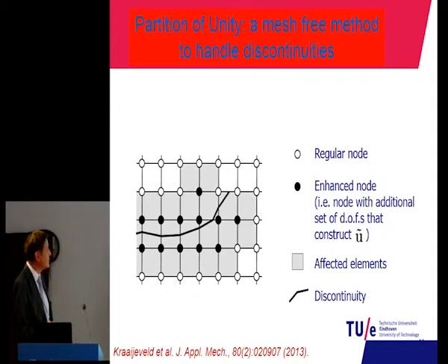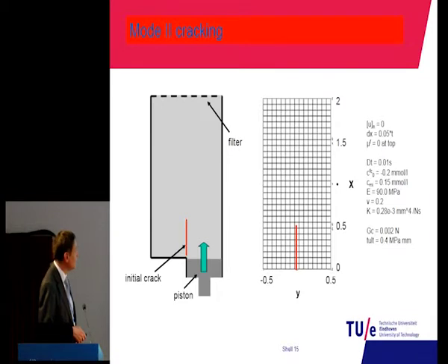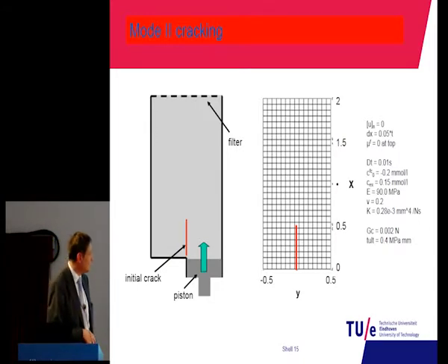And we assemble our system this way so that we can actually eliminate the fluxes element by element and be left in the whole system of equations only with displacements and those three Lagrange multipliers that we use to get these fluxes strictly mass conserving. It is lambda f, lambda plus, and lambda minus.